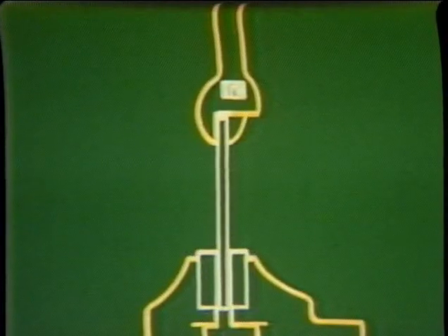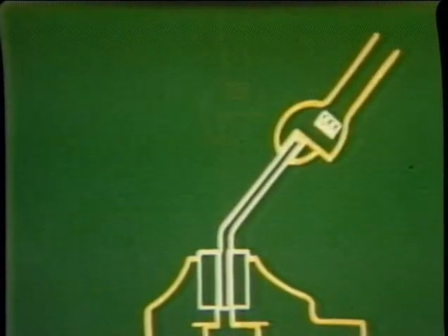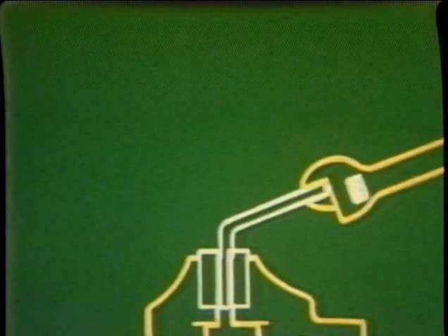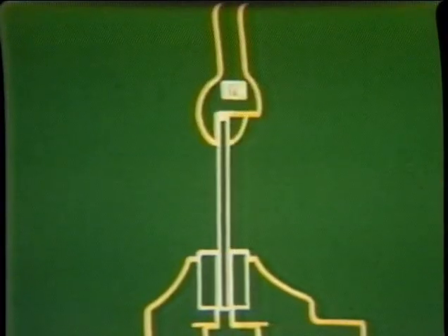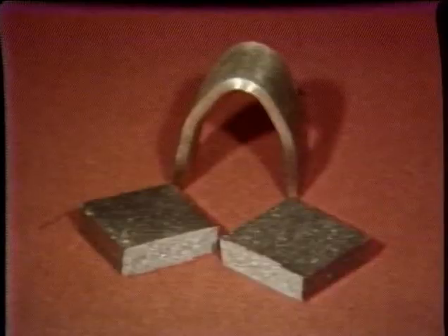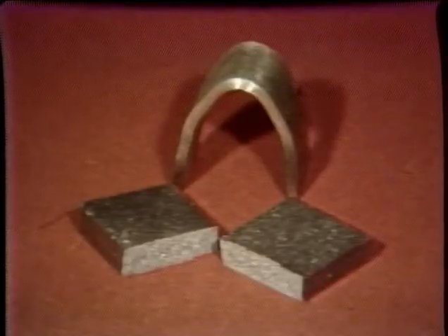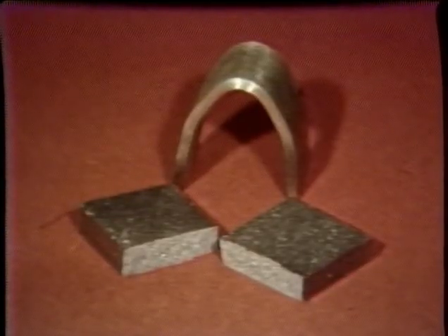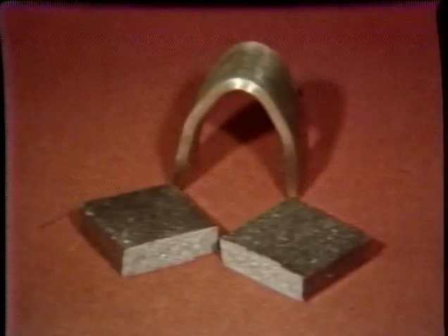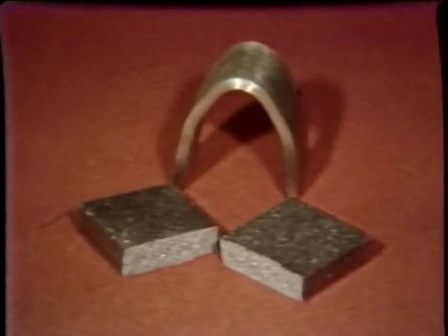Ductility is the property which allows metals to be drawn or stretched without rupture. A ductile material can be bent. A material which is not ductile is referred to as brittle. Brittle materials will fracture suddenly when bent. Steel and cast iron are both strong metals, but cast irons are usually more brittle than steel.